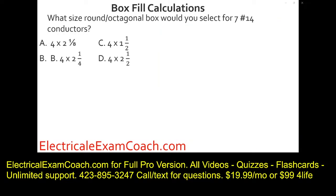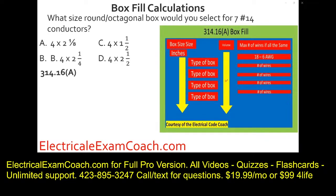What size round octagonal box would you select for 7 14 gauge conductors? We're going to head to table 314.16a. We're going to start here on the right-hand side and we're going to find our gauge wire. Then we're going to come down and find a box that fits it, and be sure when we cross over that we stay in the right category of box, and we're going to select C.